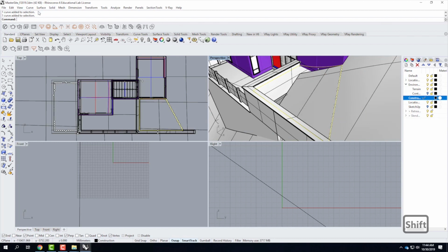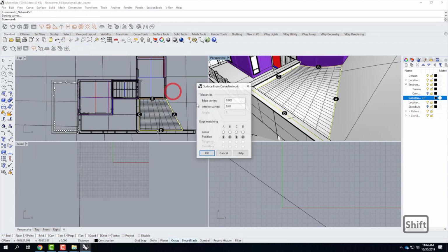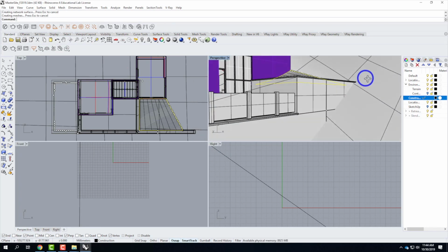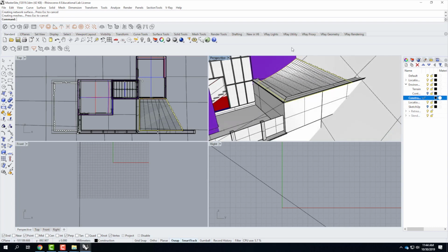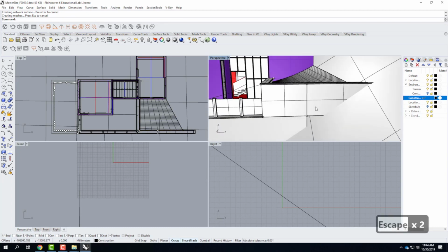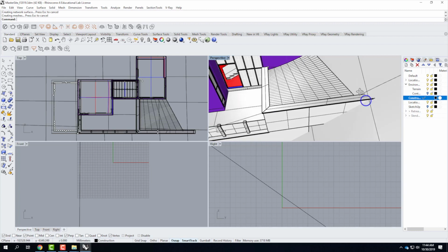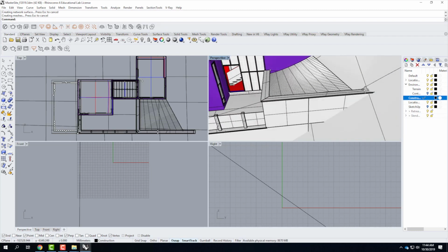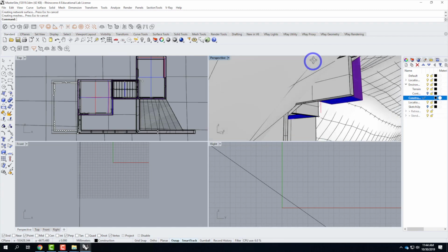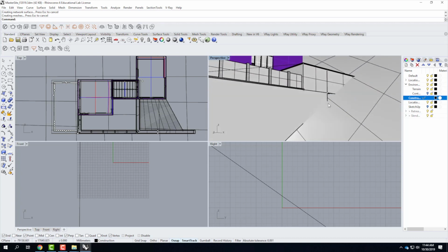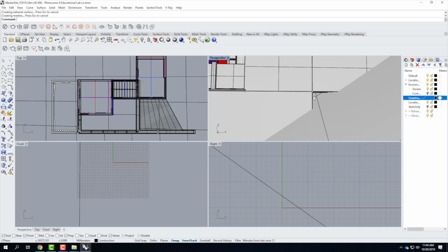So I'll go ahead and go up to Surface, Curved Network, and I'll say OK. And I've now modified the terrain in a seamless way, because I started with that projection, so that it flattens out in this little alcove, which was something I wanted. So the point is that you can trim out sections and you can cause something to kind of be adjusted as necessary. I have another problem with this model, and that is that right here I don't have enough below.